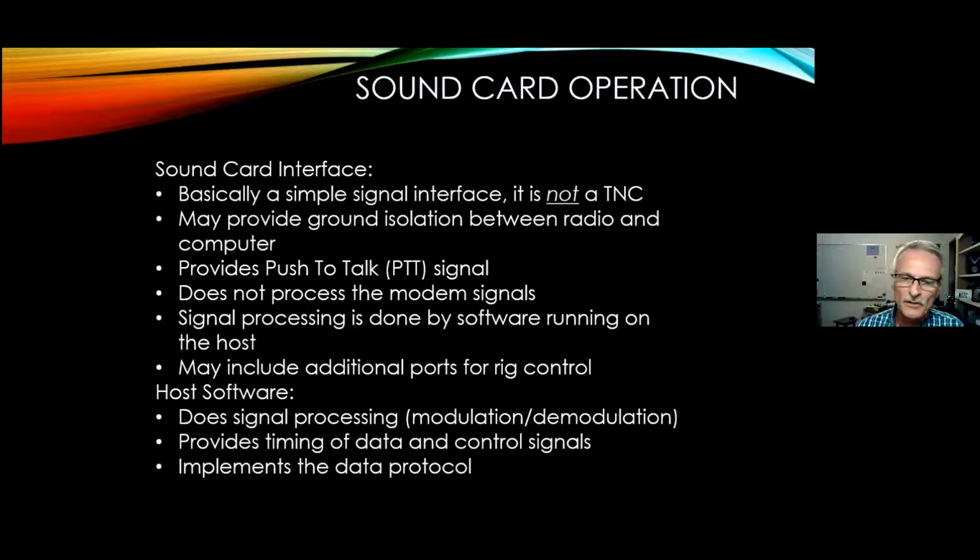So I want to talk a little bit about exactly what a sound card interface is and what it is not. There's sometimes some confusion here, and basically it's a simple signal interface. It is not a TNC. A lot of times I'll have people call me up or send me an email and say, hey, I'm having trouble getting my SIGNALINK TNC working, and I usually respond with something nasty like, well, that's because it's not a TNC. It's really just a very simple signal interface.